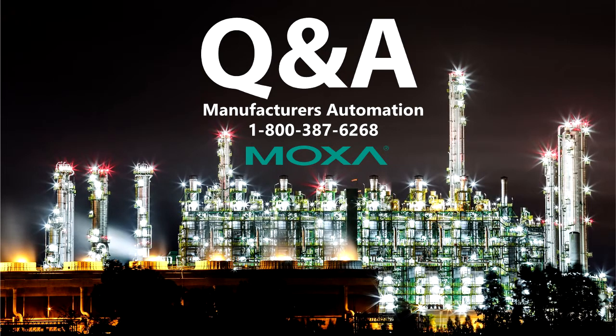Not to mention that capacitive requires a strong connection with the electromagnetic pulse of a human body, so your fingers. So even if you're using a bare hand and say you sweat or there's water on the screen, it's going to interfere with that. You're not going to have a strong command to the HMI. That's changing. We're actually gaining the ability to have multi-touch functions with resistive screens, so the functionality that you like, say with a dry hand on your iPhone or your iPad, will be possible in the future with resistive touchscreens.